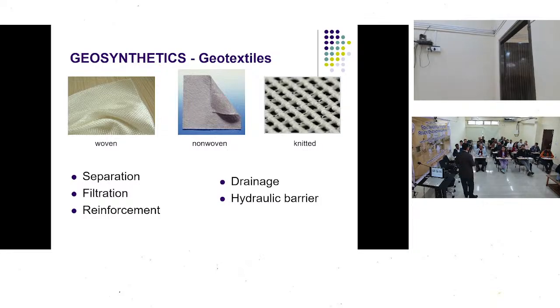Okay, fine, great. And which will be thicker? The non-woven will be thicker. Fine. So we have a woven type of material which has more strength, and a non-woven type of material which has relatively less strength but is thicker. So I can use the non-woven material as a cushion, as puncture resistance, between my granular fills, to protect my woven material from damage by puncture from the irregular shape of the gravelly material.